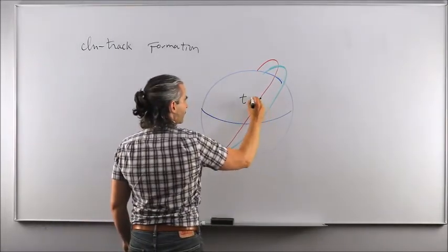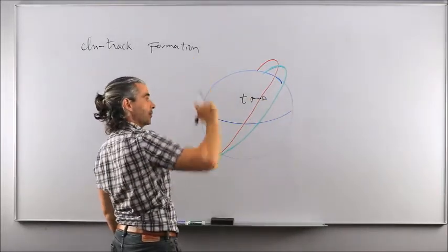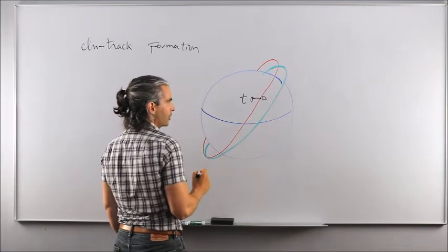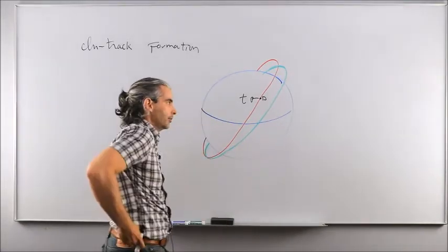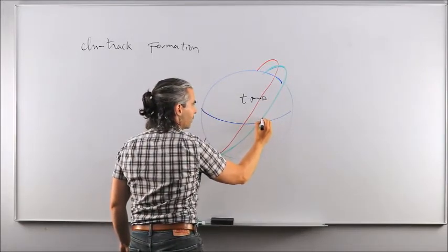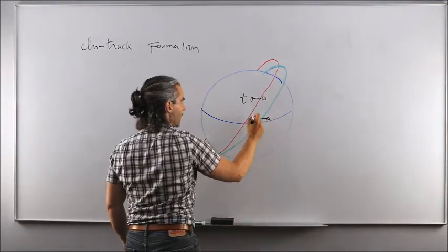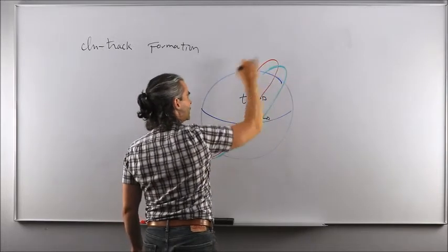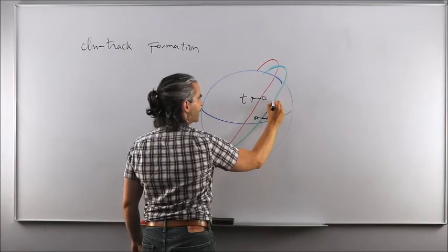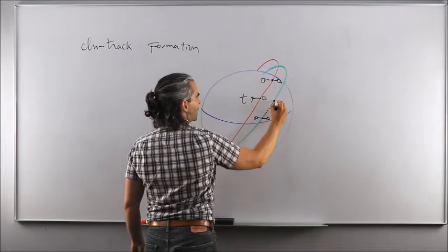While here, spacecraft right over Ottawa sees us, wave at the spacecraft, still over here. It says time equal t. And then we want the other spacecraft of the formation to also fly right over Ottawa, but at some time in the future. Which means that the second spacecraft must be behind the first one whenever this one is right over Ottawa, such that once this one is past Ottawa and flies up to the north, as the Earth rotates, the spacecraft would advance and eventually hit the same latitude that spacecraft 2 was sometime in the past.